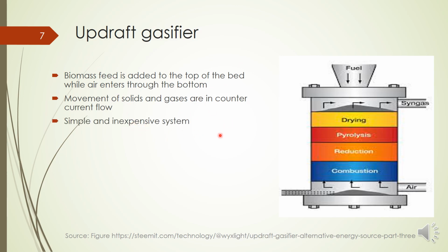And these are the first developed gasifiers, and very easy to fabricate and inexpensive. And they also offer high carbon conversion efficiency, meaning how much percentage of carbon is converted to gases, and the gasifier efficiency is also high, and they have a low dust level in syngas. So these are some advantages of this updraft gasifier.